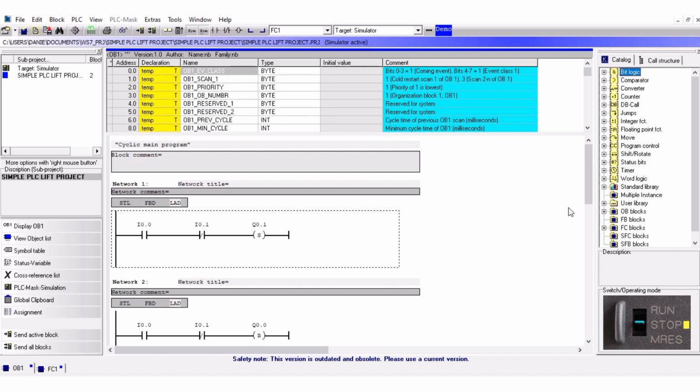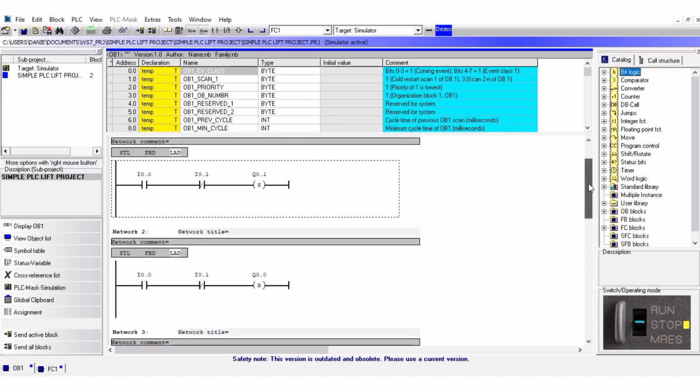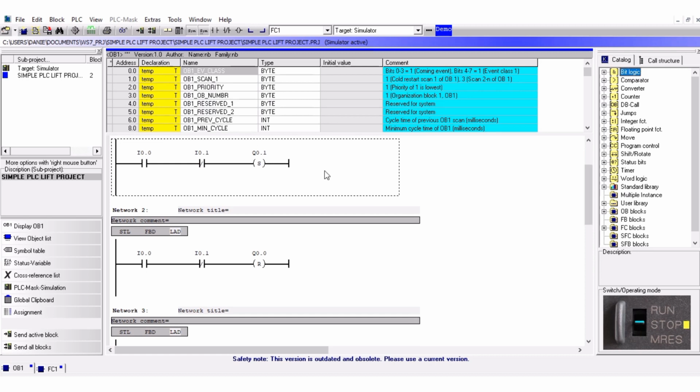That's the difference. For the other one, the normal contactor, we need the maintainer, which must be in parallel with the button, so that when the button is released, the contactor will have already closed the maintainer, and it will remain on. So that's the difference.